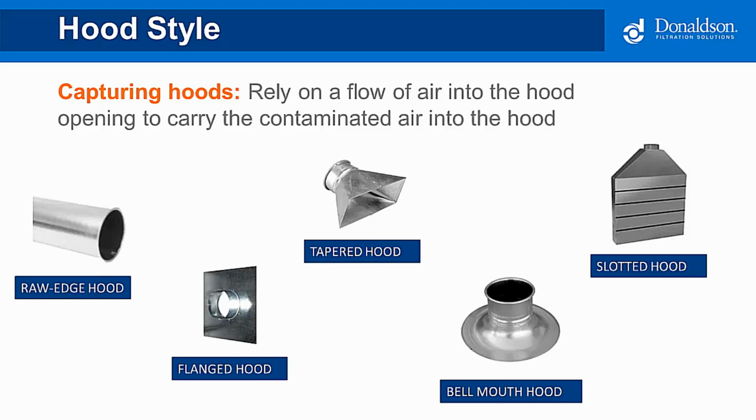And I know by looking at the poll earlier, there's a lot of people on here that have wet grinding applications. So we typically want to design that hood so that we can get as close as possible to the application without interfering with the process. And we want to provide just enough airflow to capture that mist into the hood.